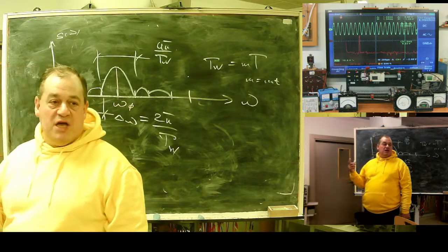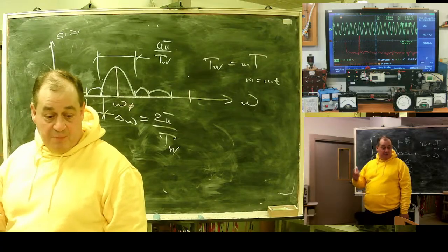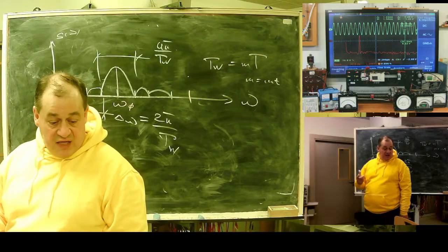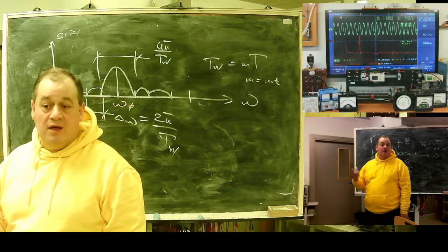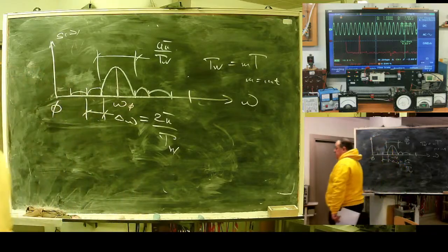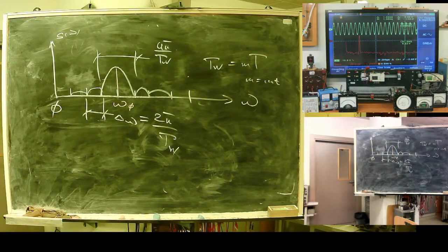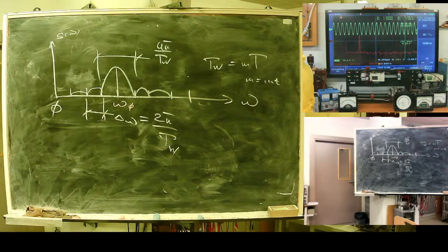You can measure frequency, have one independent channel for net frequency, and according to the measurement select the number of points per frame. It's when high precision is needed. It can be a trick: adjustable length of the observation window to get the end point exactly at a period.